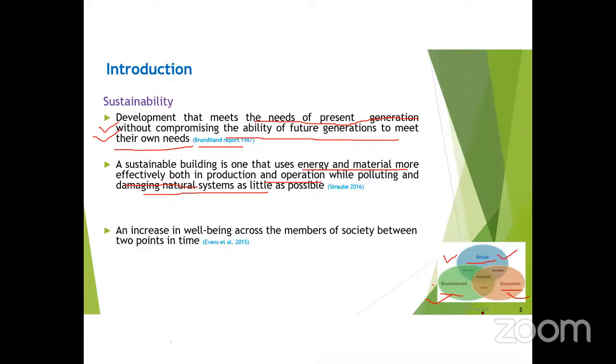Yes, green costs more when we compare it with the conventional building. But whenever you calculate the payback period based on electricity bill cutting and property tax saving, in PCMC and Pune areas they have a premium for green buildings. If your flat has a solar water heating system, then you get property tax benefits. Such incentives the government gives us so that you can go for green construction. And yes, for a 3-star building, the payback period is as low as 2 to 2.5 years.